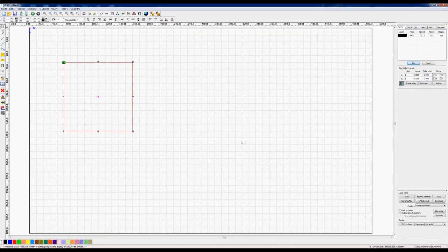If you just follow me down to the bottom right hand corner here, we find that we get a little box which has got position in it. And if we open it up, we'll find that there are not just one, but there are actually 4 positions in here. I very much doubt whether many people will have actually been down there and looked at these, because you've never had a problem with your machine. It's always been set to current position. Now, what does that position mean? Well, that is actually the position of this green square, the starting point for your program.